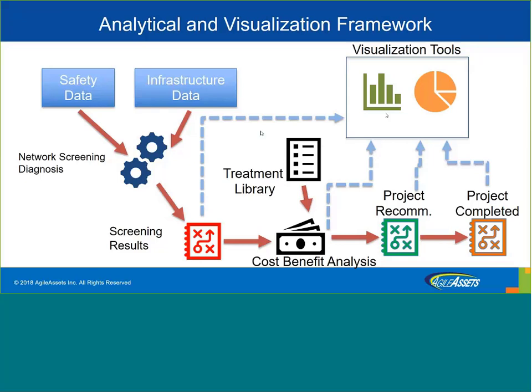So generally speaking, you need crash data and the roadway inventory data to run this analysis. It will be best if you have the crashes geocoded, which is you have the locations like route, milepost. That information will help in running this analysis.